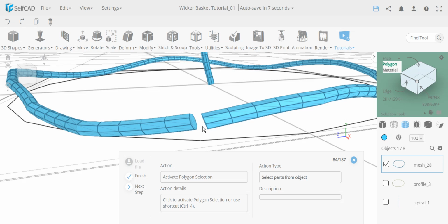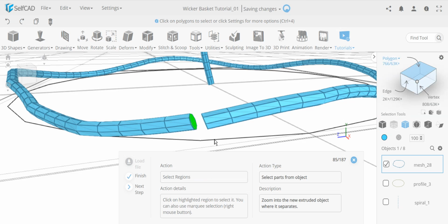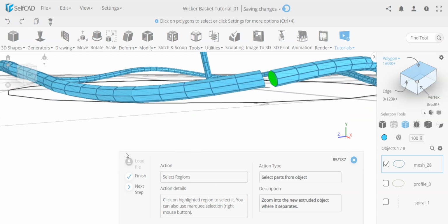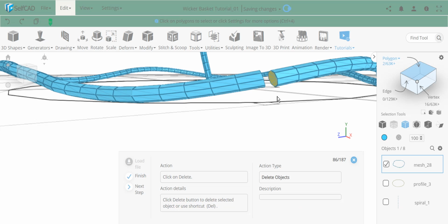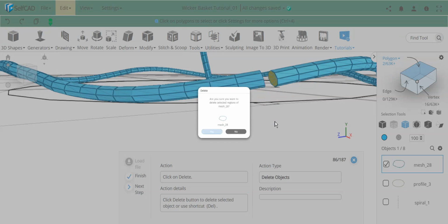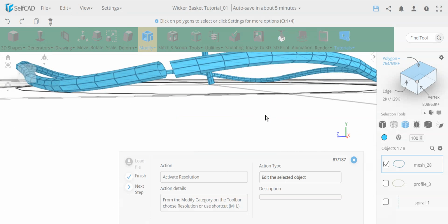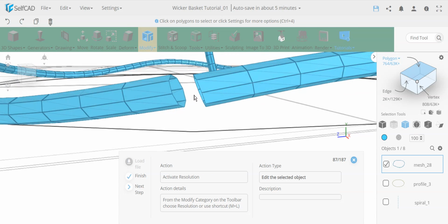We didn't use advanced settings, just the basic settings. And in this case, it left this open over here. So it's going now to use polygon selection because there's a lot of faces here. In Polygon, you can select an entire thing together as long as they're flat. It's selecting these two, and it's going to delete them. So I'm clicking the delete button, and you could have used the button here or just the delete key, doesn't matter. And the goal here is to bridge this gap.